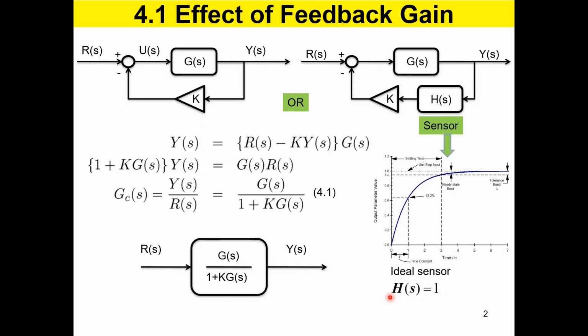Now, if you look at these mercury thermometers that you use to measure body temperature, they are not of this category. They are a different type of category because they are not going to be part of a control system feedback, just to measure. So you can wait a couple of minutes to get the reading. We are referring to feedback systems. So therefore, temperature measurement or whatever other measurement has to be different sensors, and they should give instantaneous response.